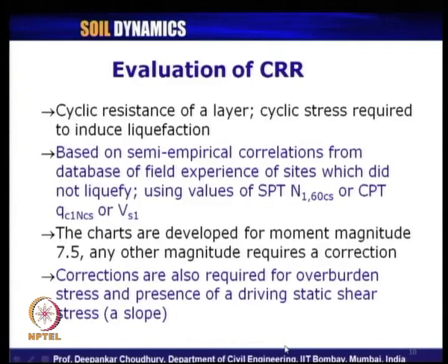2001. Then we have seen the steps to evaluate the cyclic resistance ratio or CRR. We can compute the value of CRR from field test results: the standard penetration test SPT N value, the cone penetration test CPT q value, or the SASW test, from the shear wave velocity Vs value. And remember, from all the corrected values of these data, we can correlate with respect to CRR and then compute the factor of safety against liquefaction.